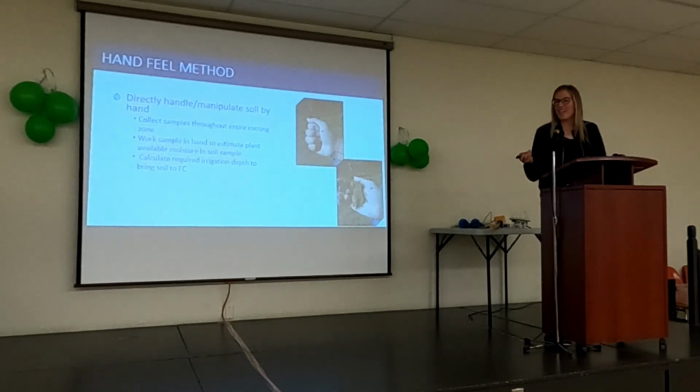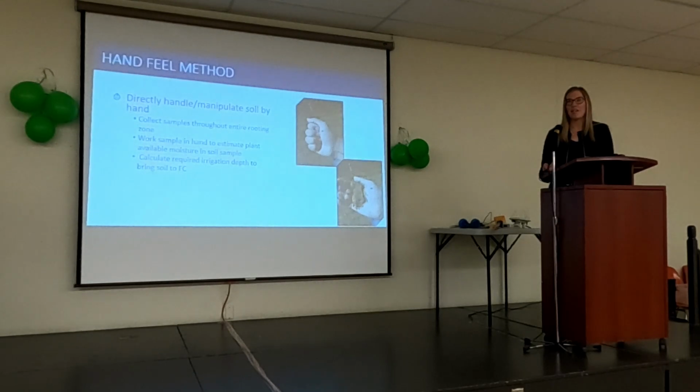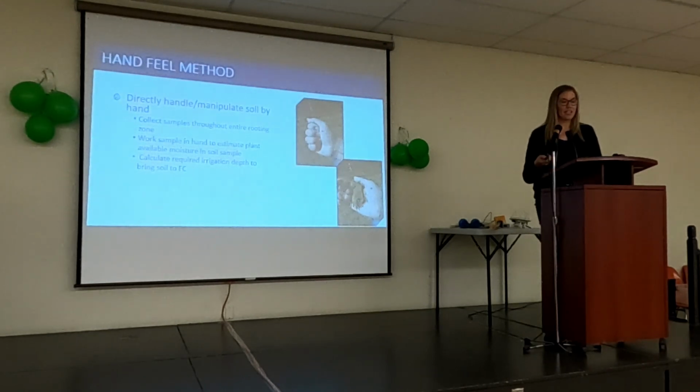And then next up is the hand feel method. So Kara already did a wonderful job of describing this, but very briefly, the hand feel method allows you to estimate soil moisture just by directly handling or manipulating the soil in your hand. And after collecting samples through the rooting zone and estimating your plant available water, you need to calculate the required irrigation depth to bring that soil back up to field capacity.